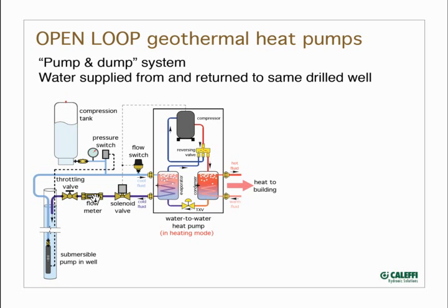Silt, sulfur or hydrogen sulfide, various bacteria, this can all end up plugging up the heat pump. And specifically in the cooling mode, when the hot refrigerant is going through that water-cooled condenser, that's where you tend to plate these things out. So make sure you have the water tested for quantity and quality before you commit to that.